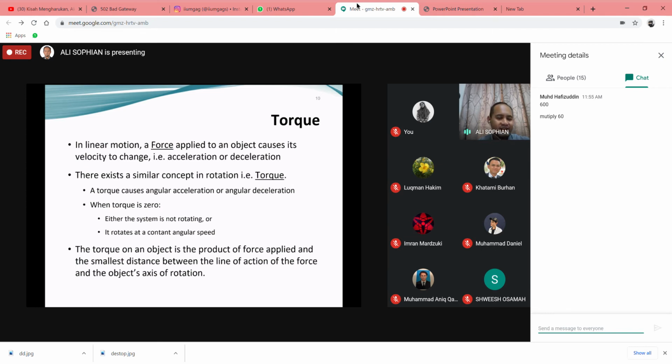Okay, so that's a good answer. And again, it will be very relevant later on when you design robots or things that move on the floor, and you will need to know this in some cases. But generally, when we talk about robots nowadays, we just buy them. But probably there will be some project for you later on to calculate the frictional force and then determine the torque required from your motor.